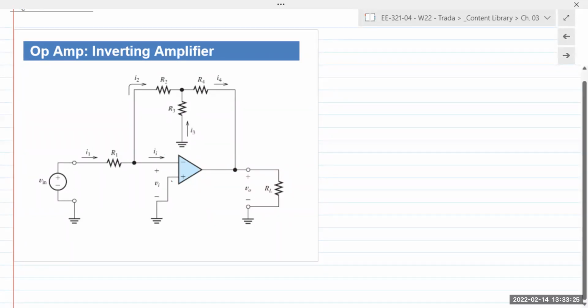Then the assumption is, of course, that the difference of the voltage going in the 2 terminals is 0, and so is the current going into the op-amp terminal, right? So negative feedback, check. Assume V in is equal to 0 and I in also equal to 0. I in this circuit is noted as Ii. That i, again, is just a subscript of input.